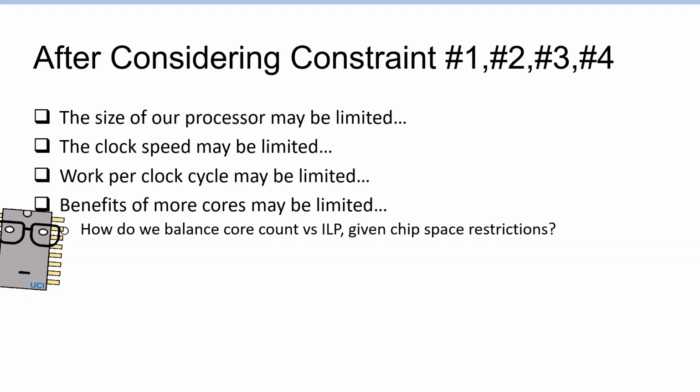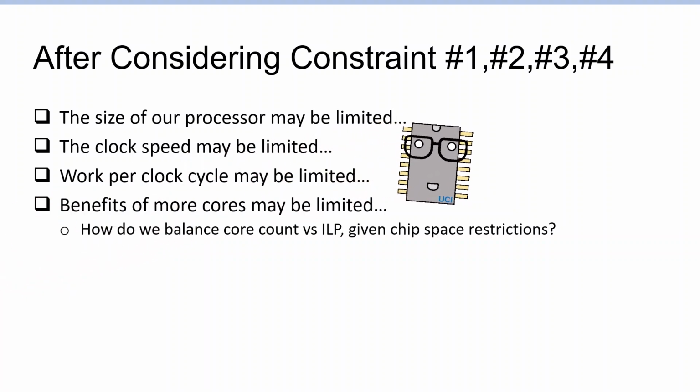If we can design the ISA in a different way, or if we can architect the microarchitecture in a different way to get us more performance, higher clock speeds, even if you have to sometimes spend more chip space on it in regards to differently architected processors or more pipeline registers, etc., we can turn that knob as well.